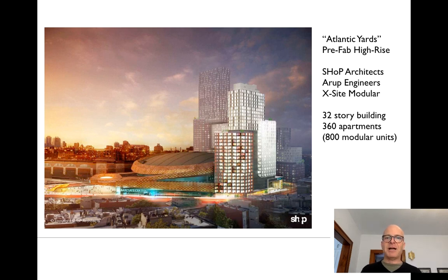SHoP and Arup not only designed the buildings, but they also designed a lot of the process. And some of that even involved developing apps where they could keep track of individual prefabricated units. So on a very, very tight urban site, right in the middle of Brooklyn, right next to the Barclays Center Arena, they, of course, have to keep track of where all the modules are. They can only put a few of them on site at any given time. And they want, of course, to be able to use the crane constantly. Right? The cranes are expensive to have on site, and so you want to make the most use of them in the shortest amount of time possible.